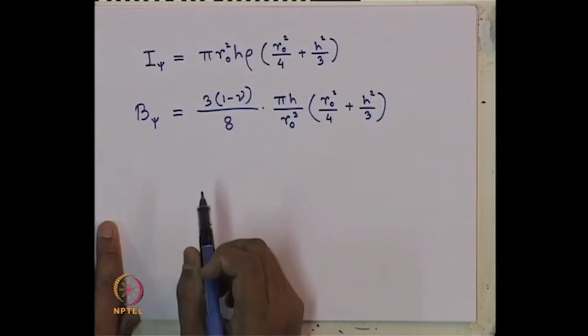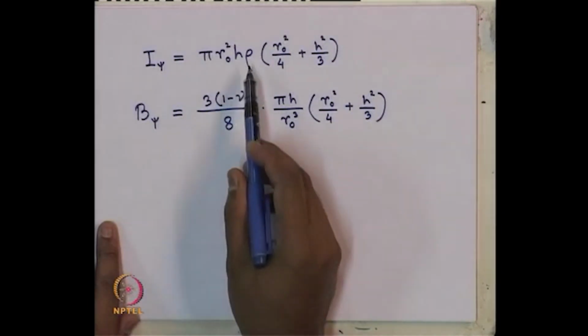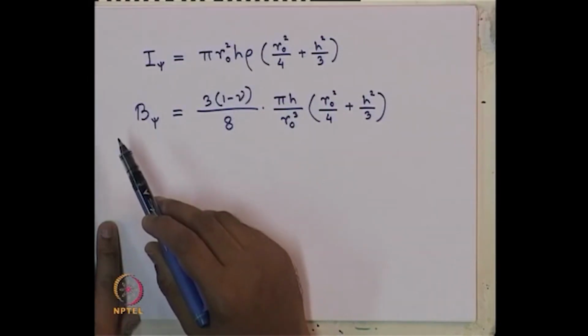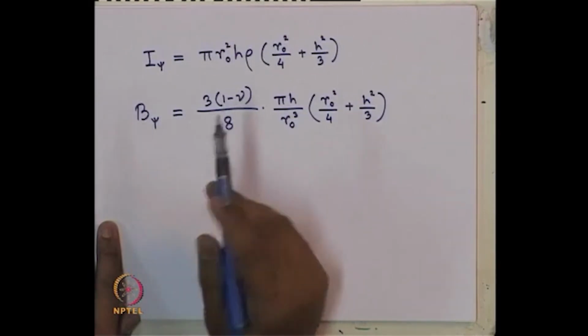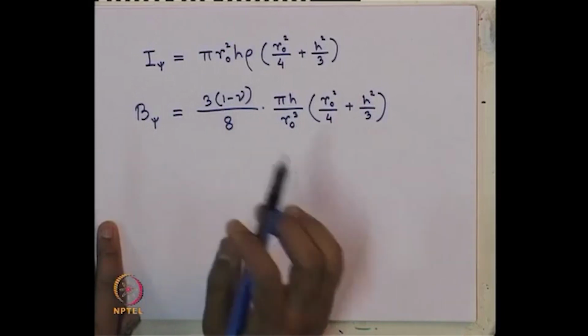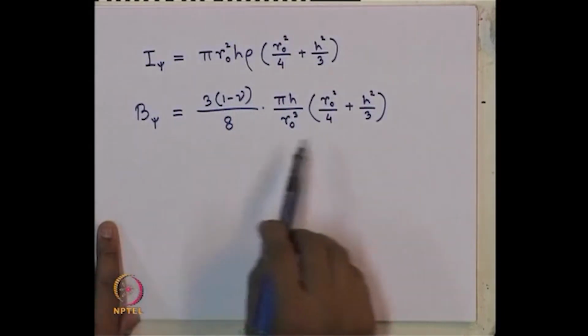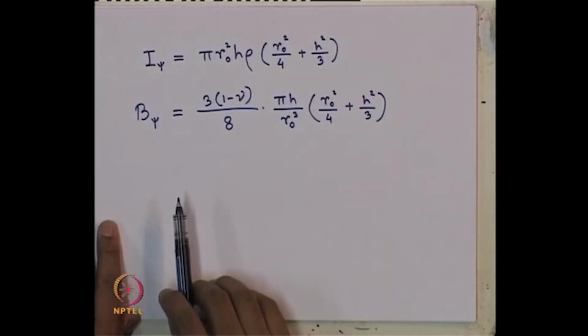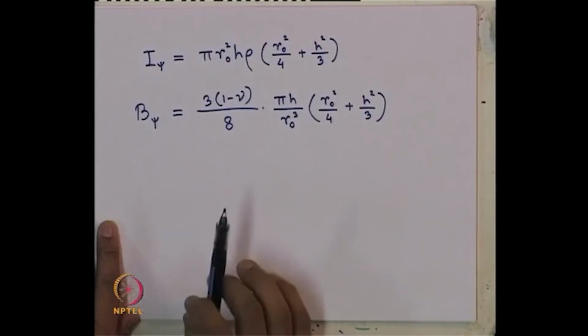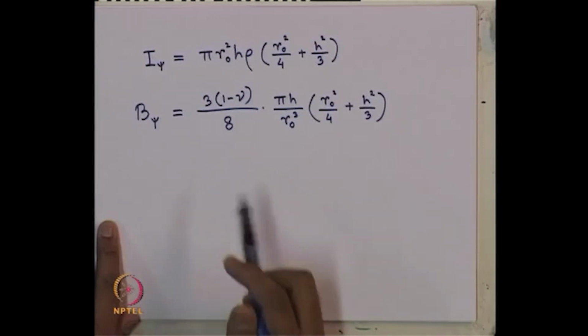Here I have made one assumption. This rho will be rho for foundation, whereas in the other case of B psi, the expression the rho is for rho of soil. So, I have considered both are almost of the same order and equal, so I cancelled it from the expression to simplify the expression for B psi. So, remember this. Otherwise, also you can take the exact value, there is no harm, truly speaking.